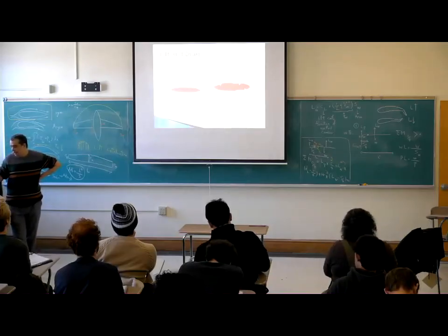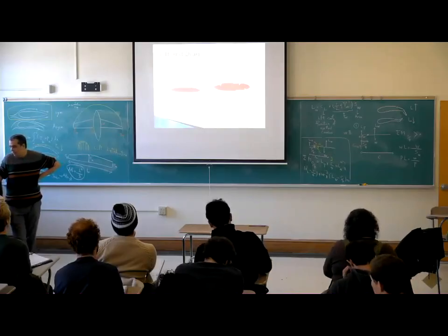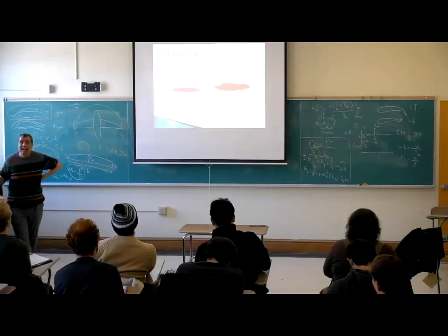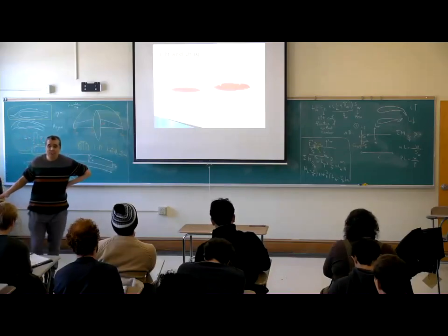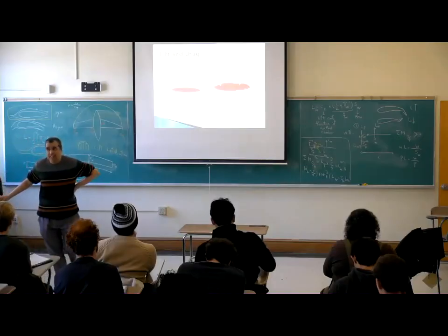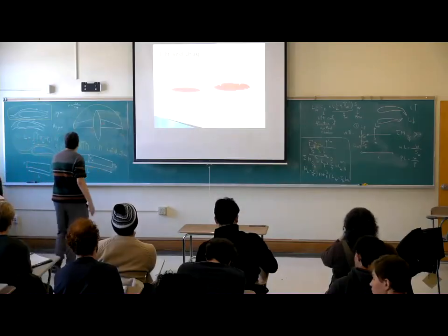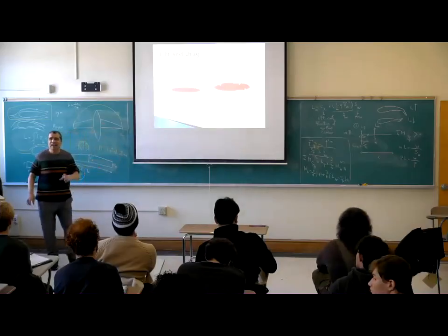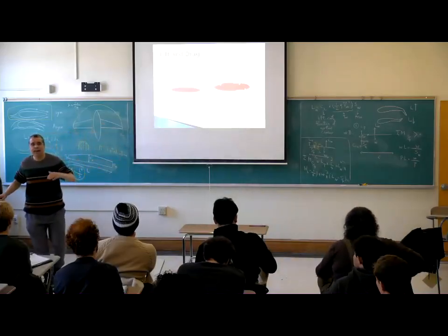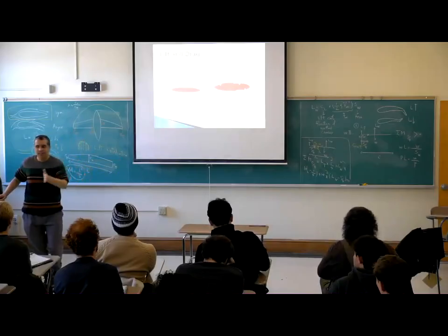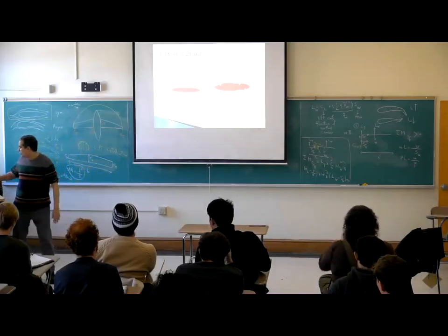As you see here, the boundary layer can create some. Pay attention. Airfoil drag is mostly due to viscosity. Cylinder drag, I clean here. Cylinder drag is mostly due to the pressure imbalance on the left and right.